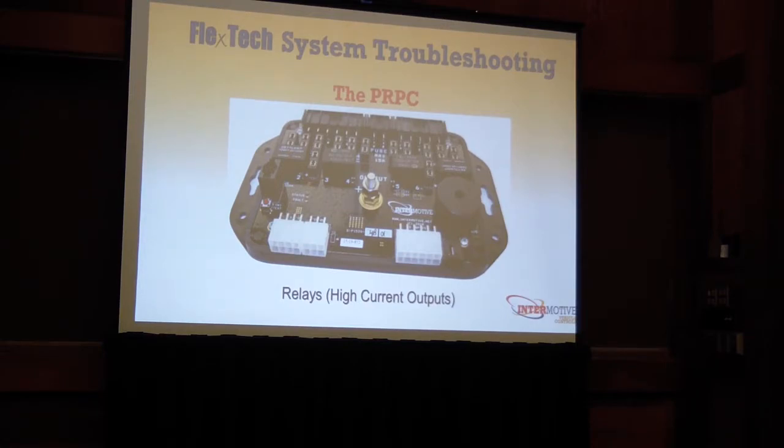So you can see the fuse up top, the fuse holders. Each of those fuse holders has an LED next to them, a red LED, and that's a fuse blown LED. So if you're not in a diagnostic page, then that's what those LEDs mean. The fuse is blown, right? If it's on, check the fuse, replace it.